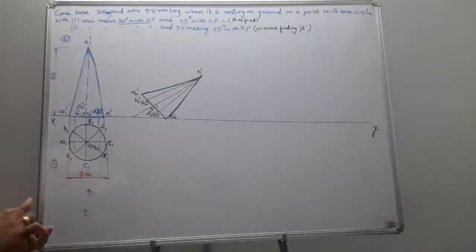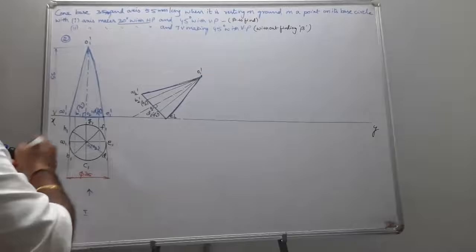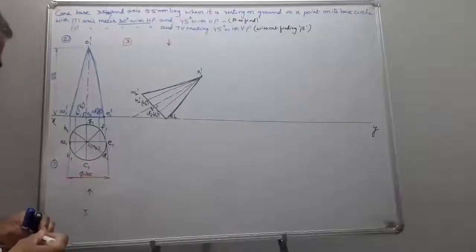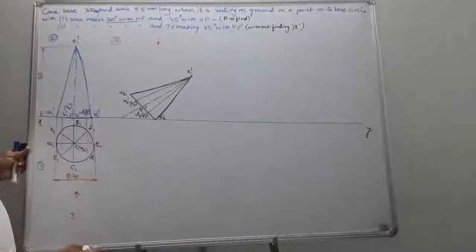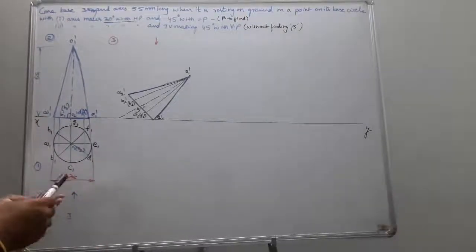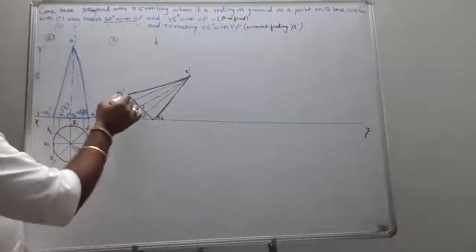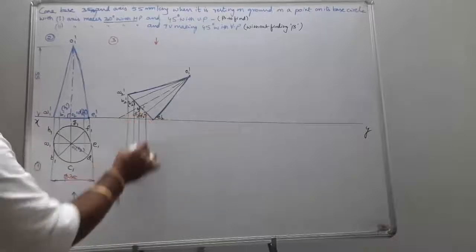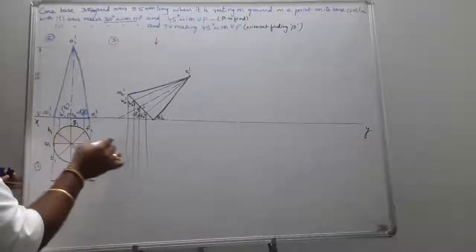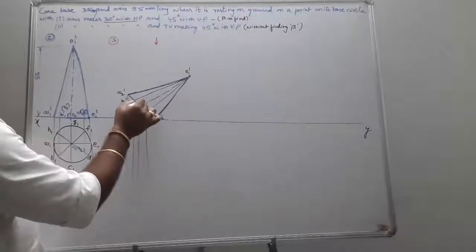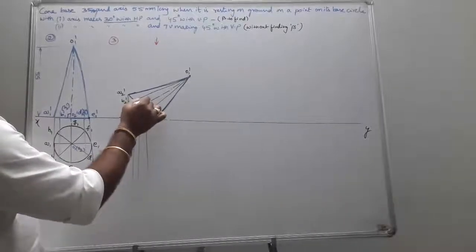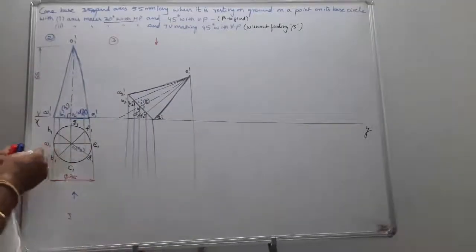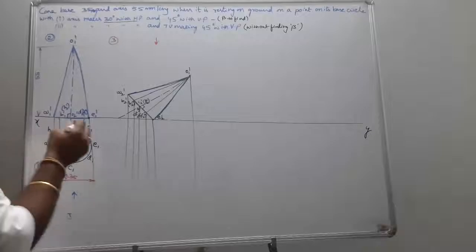And when I am supposed to see the top view, this is your third step. How can you obtain your top view? Draw the verticals from here and draw the horizontals from the previous.